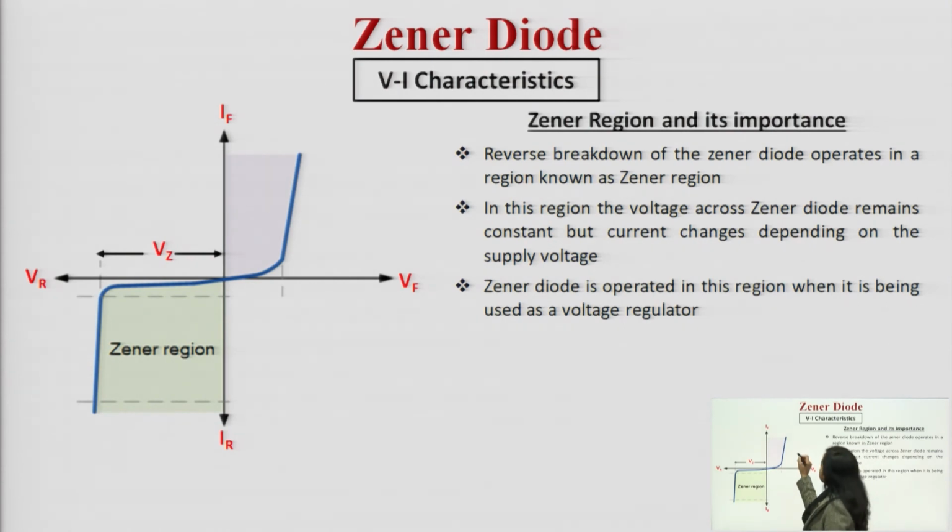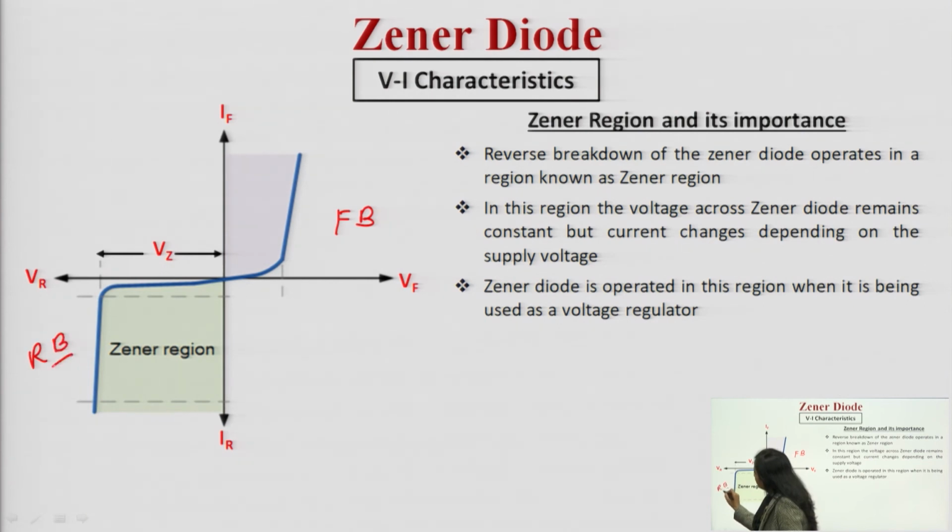See, this is the forward bias condition. The characteristic curve is almost similar to the PN junction diode. This is the reverse bias condition where the Zener diode operates, and it looks like this. You can see this is the breakdown voltage, Zener breakdown voltage Vz, and here you can see the current increases sharply and suddenly, right? But practically you cannot see this line as a perfectly straight line, there is a relative slope over there. So, this is how you can draw the VI characteristic.